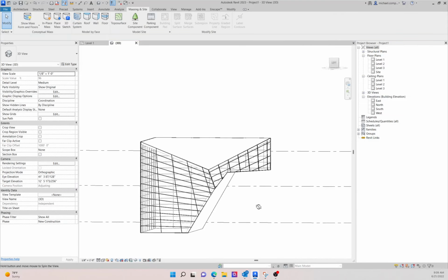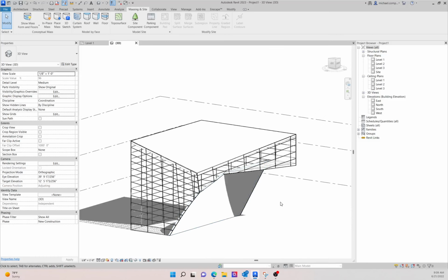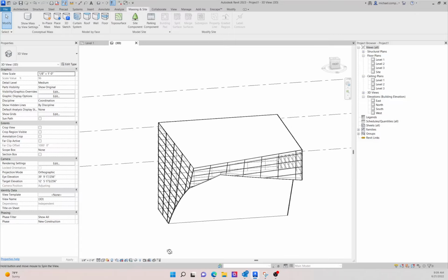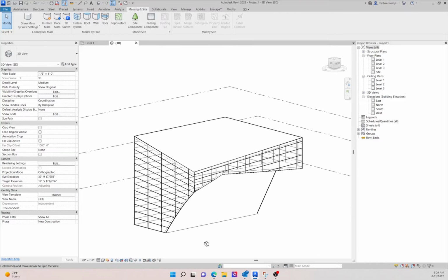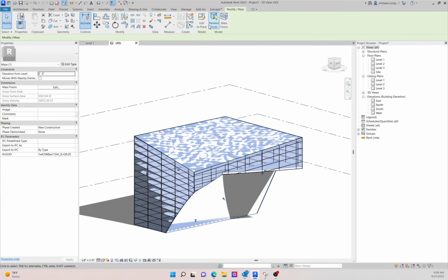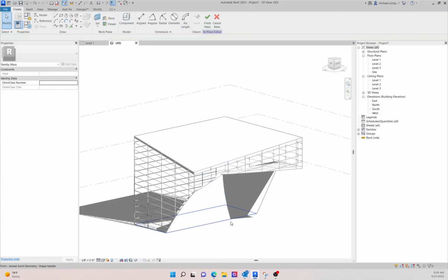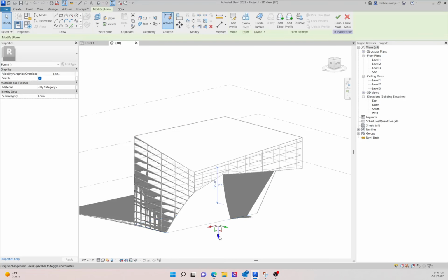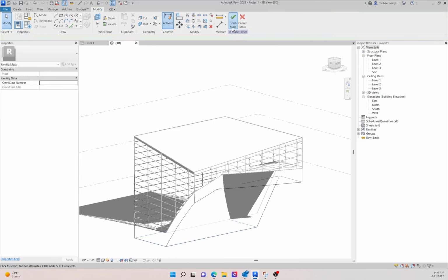So as you can see, it's a pretty powerful tool. Now, let me offer one more thing. Oh, by the way, under the mass tool, this is the show mass toggle. So if I uncheck that, then the mass, or the balloon part of this papier-mâché, goes away, and you're looking just at the architecture. But if I toggle it back and I try to manipulate it, here's what I mean. I'm going to tab through to select the mass. I'm going to edit the mass, and I'm simply going to pull this geometry down a little bit. Okay, I'm going to finish the mass.